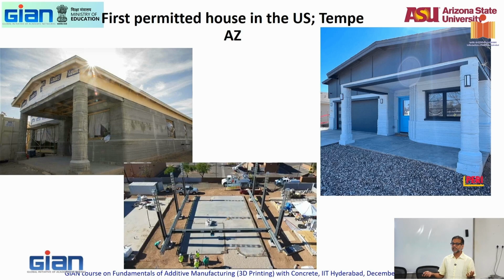We did a lot of testing in our labs for cracking, for strength development. Strength was not developing, because the city wanted strengths that are much higher than allowable concrete strengths because there was nothing in the code for this. So they want to be safe. They said without 4,000 psi, we're not letting you print. And then to get 4,000 psi on a mortar, which was cracking left, right, and center, was challenging.